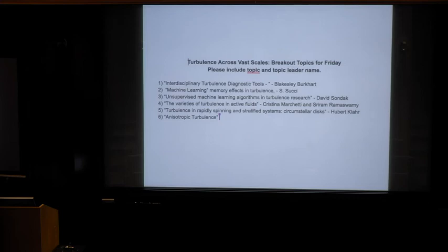All I'm saying is that in real life, most of your experiments, and for that matter, in many of the problems I'm dealing with in soft matter now, Reynolds is 10 to minus 4. In the numerics, we know for a fact that keeping U grad U, the inertia, alive helps a lot. And Tony Ladd, who is a colleague in Florida, once gave me the point, the reason I cannot reconstruct, but it was a very cogent point, that that term has to be there. I'm talking now numerics. Is that just closure correction or something else? Well, it could. Let's say that the nonlinearity could help regularizing the infinities. I think we're talking about stability. I think so. I think so.